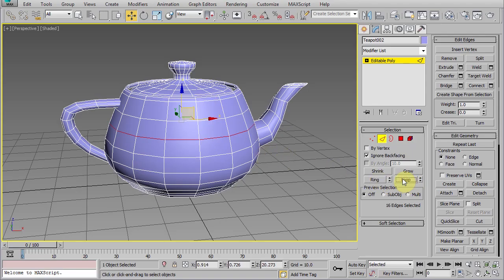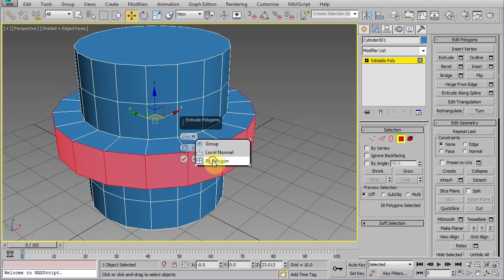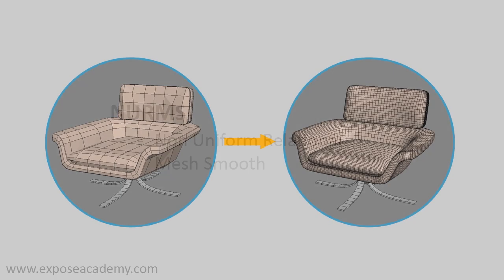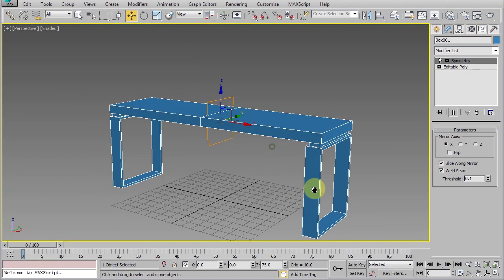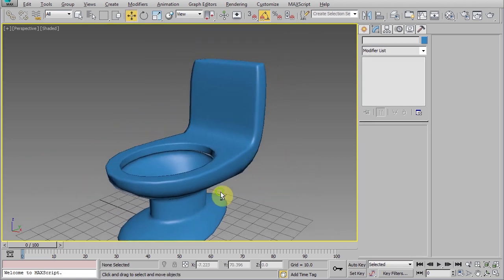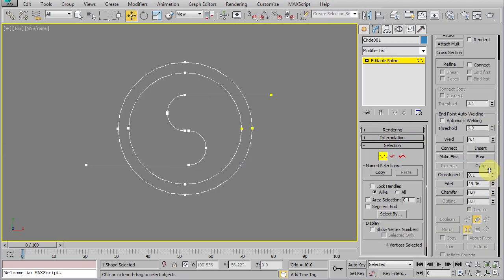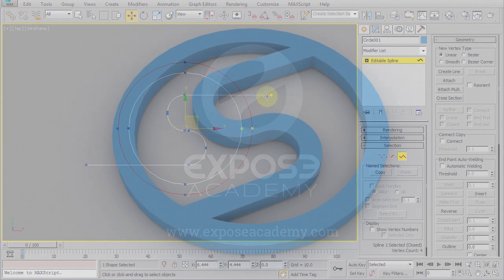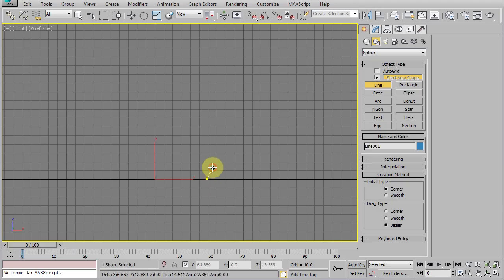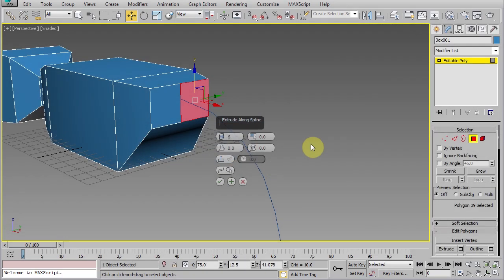After learning the essentials, we're going to move forward to 3D modeling techniques. The first technique we're going to learn is polygon-based modeling techniques. We're going to use norms and understanding the norms' behavior. After that, we're going to create some objects to practice the techniques. After mastering the polygon-based modeling, we're going to move on to spline-based modeling. We're going to reveal the Bezier handle concept in spline editing, how we can use modifiers to convert spline into geometry, modifiers such as extrude, bevel profile, lathe, etc. After we understand the basic concept, we're going to create several 3D objects using spline-based modeling techniques we discussed before.